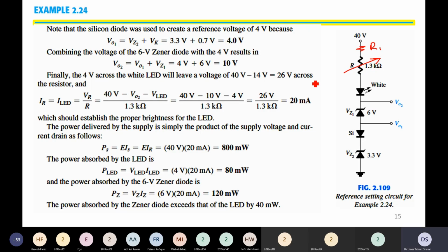So now we can safely vary R, because we have a series resistance R1. Let us say that is of 500 ohms. So now if we change our variable R even to 0 ohm, still there will be 500 ohms in the circuit and the current will be limited. This is far better than if we do not use R1 and just have a variable resistance R. So when this variable resistance R is varied to 0 ohms, there will be too much current or infinite current. So to prevent such events, we are using a fixed resistance R1.